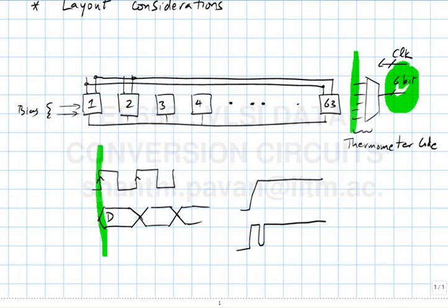So if you are working in a digital environment, and everything is edge triggered, for example, you are only looking here and probably looking there, so you don't care. This is essentially a level triggered system, right? So when the input is high, the current source tries to do this. When the input is low, the current source tries to get switched to the opposite direction. So a waveform like this is what?